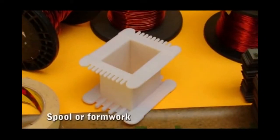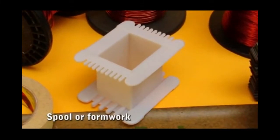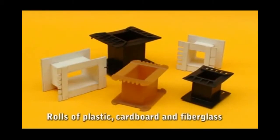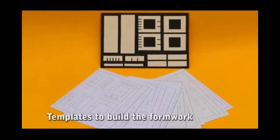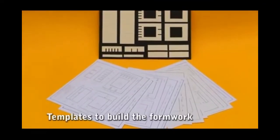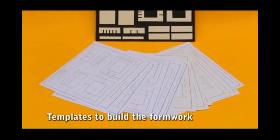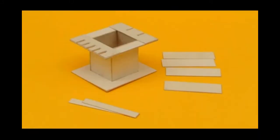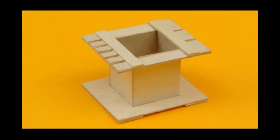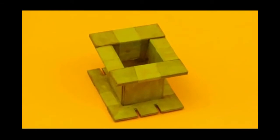Formwork. A square reel is used as support for winding the wire and prevents spreading, helping the smooth winding of the wire. The formwork is available in various materials such as plastic, cardboard, and fiberglass. The formwork design may be downloaded from our website and then built in plastic or cardboard. You must make the pieces of cardboard, gluing them with wood glue, reinforcing with masking tape and a coat of varnish which protects the reel from moisture, giving it consistency and durability.